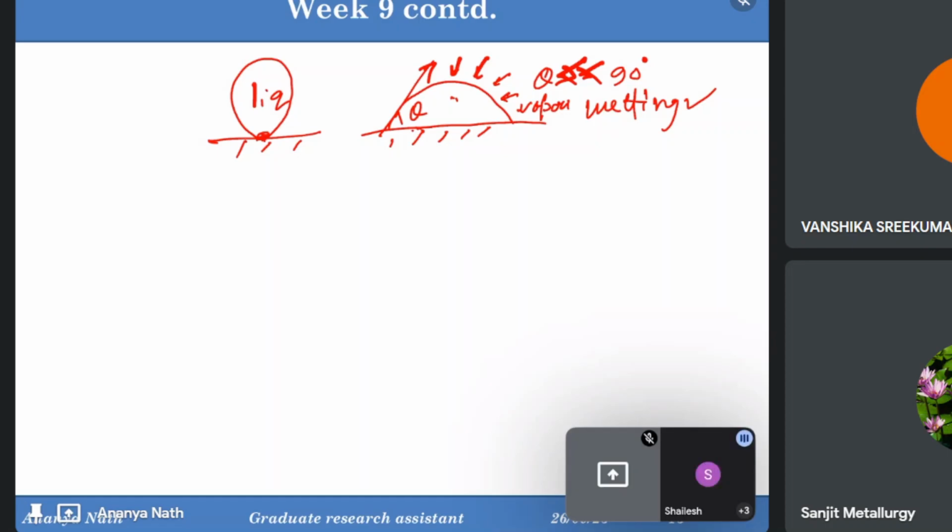Actually, ma'am, in the lecture I have seen these two statements: sometimes we are adding only silicon, and sometimes we are getting oxidation and the layers just form over the surface. Yes, you are right. It was mentioned that Si is mixed and the SiO2 coating is also mixed, and both things improve the wettability. So which one is better? I think SiO2 will be better, but at the same time, since there is SiO2, oxidation is taking place. So that can hamper the property of the SiC as well. So there can be other problems.